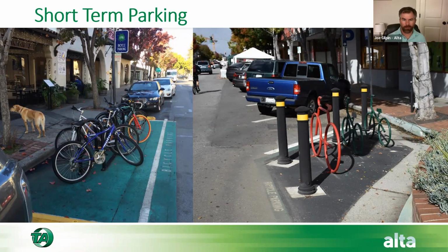But what we see typically is about 10% of the vehicle spaces would be the minimum provided as bicycle spaces for any development project. There's different things that you can do for multifamily residential versus single family residential versus commercial, and it can be based on square foot, floor area ratios, or just the number of bicycle spaces as a companion to the number of vehicle parking spaces that are already required for those land uses. So there's different things you can do there.